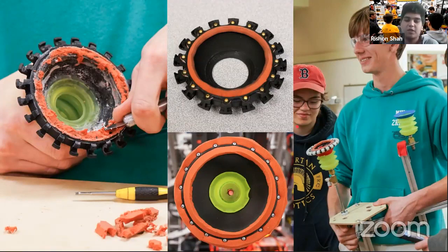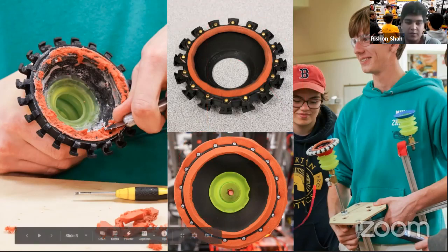So this top prototype right here, you can see that it still had the rollers, and it was one of our final prototypes, but it was also before we got rid of the rollers. It was around this time, after having a robot that could actually drive and interact with the human player station, that we realized that quick turning into the human player station and grabbing onto the ball that way wasn't actually that useful, because we could do the same thing just by backing up the robot and going back inside. So we ended up getting rid of the rollers and going to this right here, which is what our final suction cup ended up looking like.